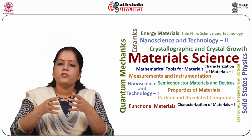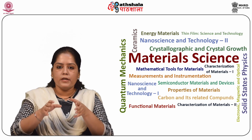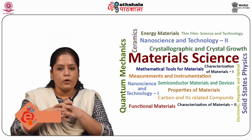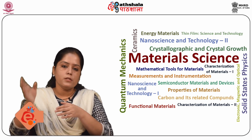Next, the effect of porosity. For low porosity, Mackenzie gave the following expression for the Young's modulus of the porous body, that is E equal to E naught multiplied by 1 minus AP plus BP square.